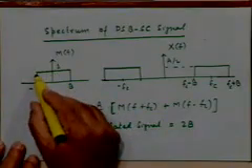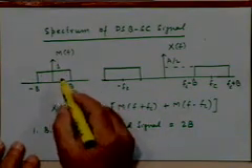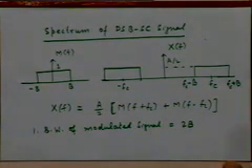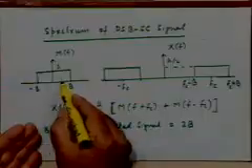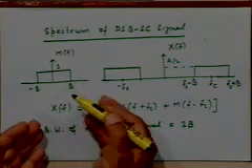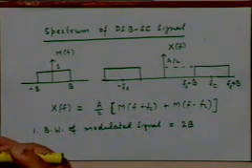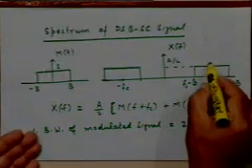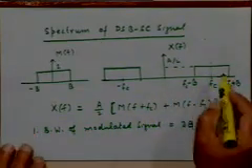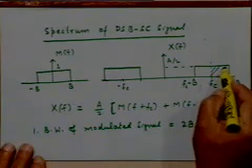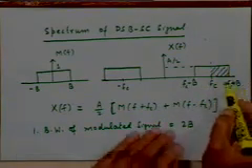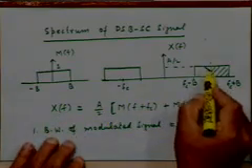Look at this basic spectrum M(f) itself. As we know, for any real signal, M(f) will have some symmetry properties. What are the symmetry properties? Its amplitude spectrum is even, its phase spectrum is odd. So if I know the spectrum on one side of the frequency axis, I also know the spectrum on the other side. What I am trying to do in this modulated signal is transmit both the sides, the positive side as well as the negative frequency side. So that's why it occupies